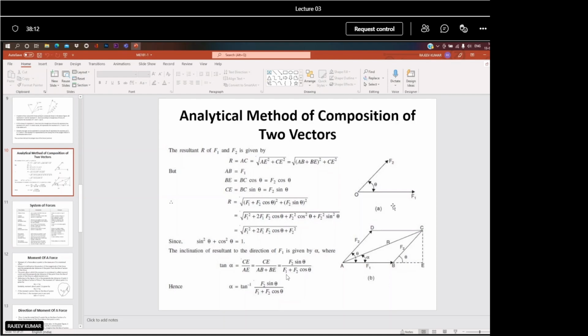For this F2, the application of force, draw the perpendicular distance from this point, because by this point you have to create the rotational effect. So this will become D2. So distance D2 will become the perpendicular distance from the line of action of the force, which you have to keep in your mind. Means if you extend this force and the point is here, draw the perpendicular from here in such a way that it passes through the point of rotation.